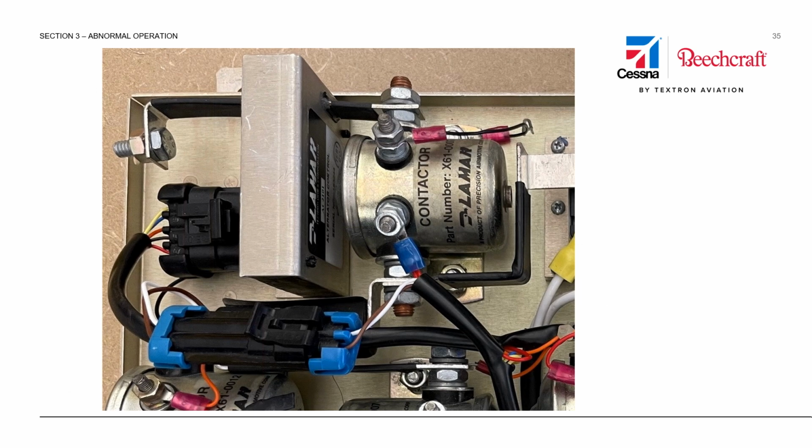One scenario that we often see in these aircraft is a complaint of a low voltage annunciation while we see 28.5 volts on the aircraft display. How can we see 28.5 volts but have the annunciation that's triggered at 24.5? Well, this is because our little orange wire coming into the top of our battery contactor here is seeing a low voltage condition for some reason. Oftentimes, it's just a condition like a loose nut or a little bit of corrosion or a bad crimp on the wire. Something is driving up resistance.